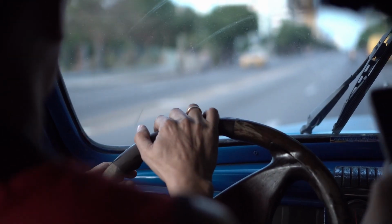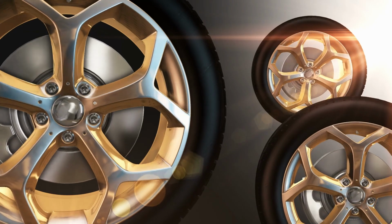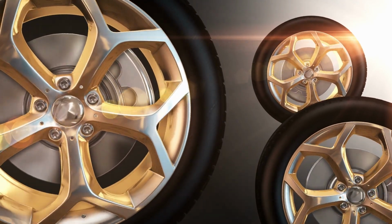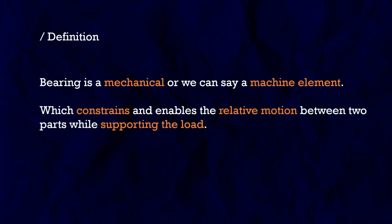We can say friction is not our enemy. Friction is very important in many applications. Like without friction, a car tire cannot run properly over the road. The car will skid, something like this. But at the center of the wheel, we need very little friction to smoothly rotate the wheel over the axle. It all depends on the application, where we need to increase the friction and where we need to decrease the friction. So this was the definition of the bearing, that the bearing constrains and enables the relative motion between two parts while supporting the load at very little friction.